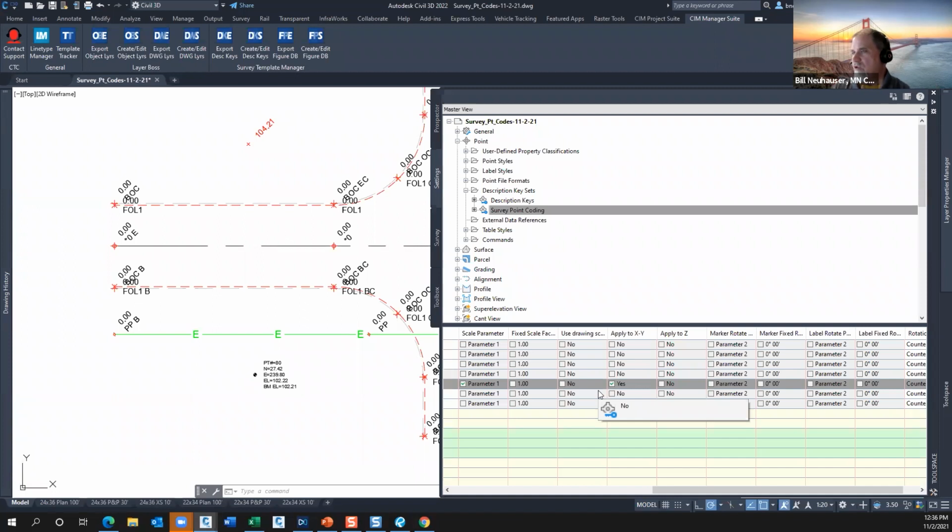Now, how do you control that? Careful. We all know architects love showing the outer reaches of the tree, these big, huge things. Civils, we kind of like to show the smaller. We like to show the stump, what's left over after we cut it off, right? So that might determine how we do a scale factor, because your internal block, how was it originally drawn? That might take some playing with to get that working right. But once it's working right, it's golden. And so again, that's how the scale parameter works.